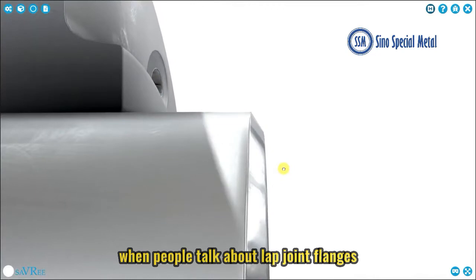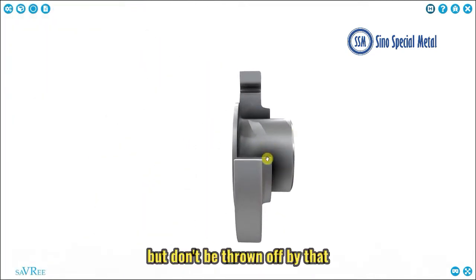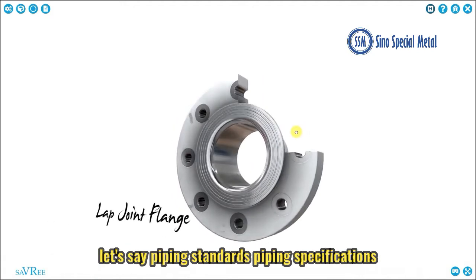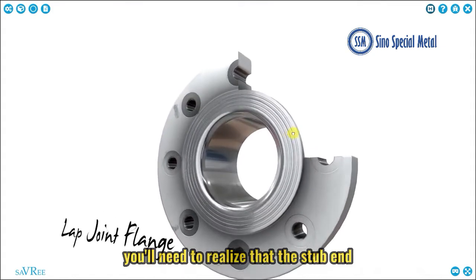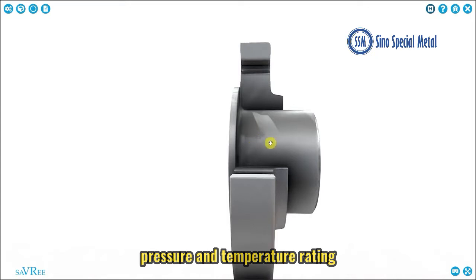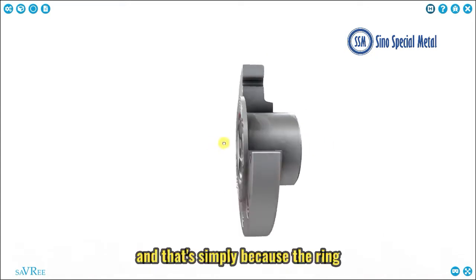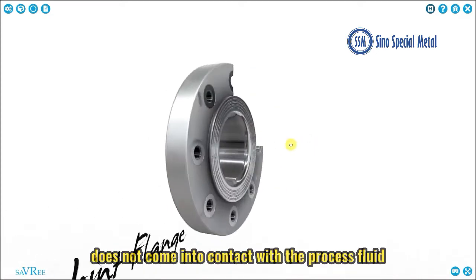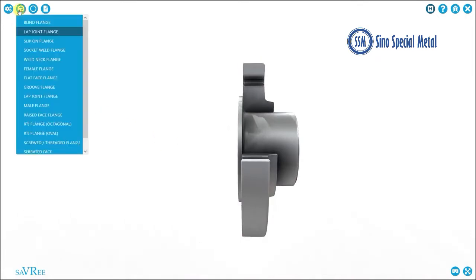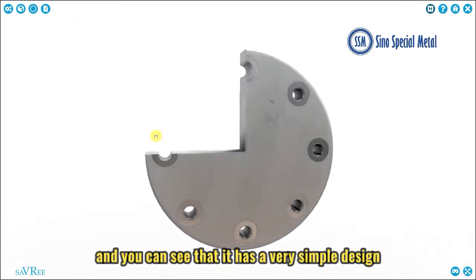Normally though, when people talk about lap joint flanges, they're including the stub end. But don't be thrown off by that, because if you're looking at literature, let's say piping standards, piping specifications, you'll need to realize that the stub end has a totally different pressure and temperature rating to the lap joint flange ring. And that's simply because the ring does not come into contact with the process fluid. Only the stub end does. And once again, we're back to our blind flange, and you can see that it has a very simple design.